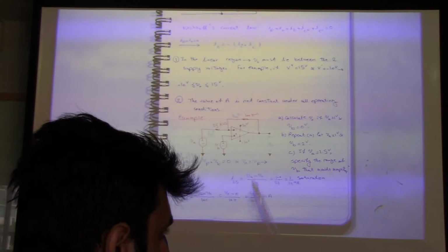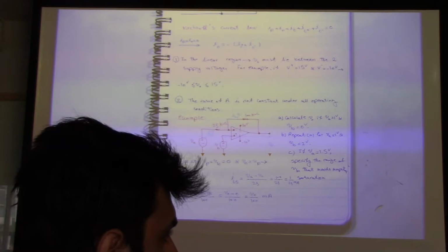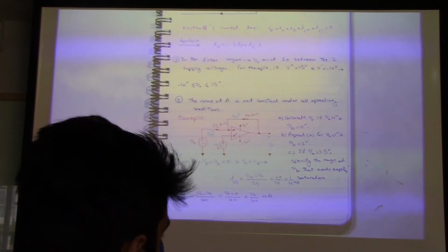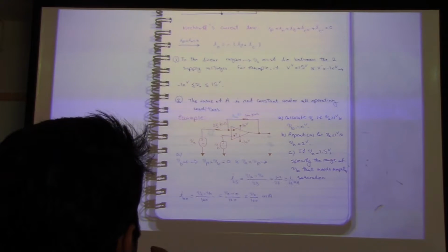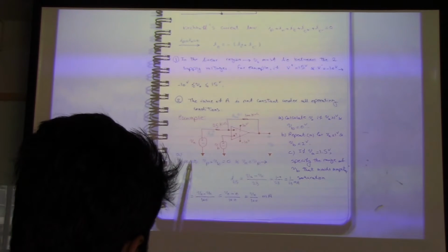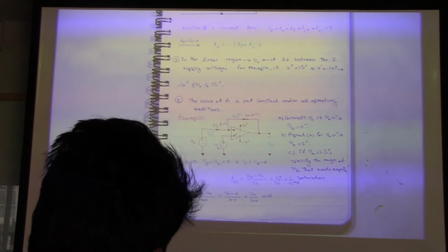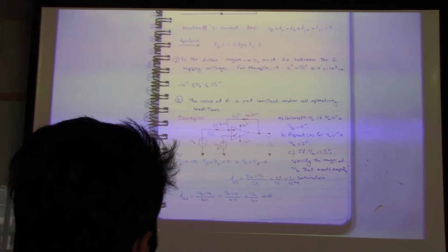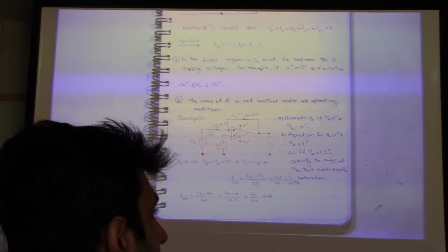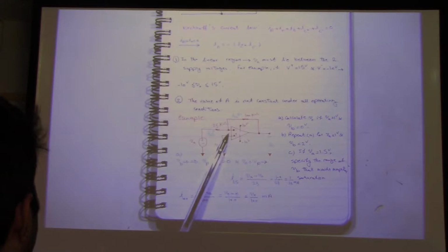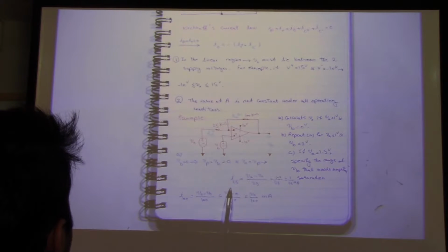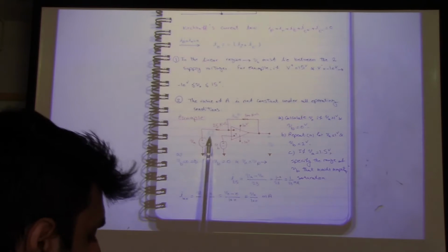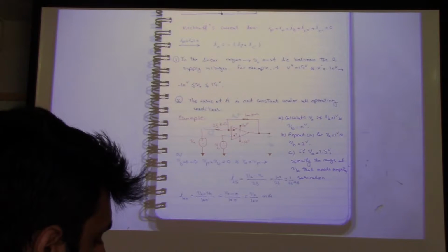Okay. So for an ideal op-amp, we say VP equal to VN. So if VP is equal to 0, then VN is 0. Okay, this is one thing. The other one, we have a constraint on current. If you write node voltage for this node, you have current I-25.